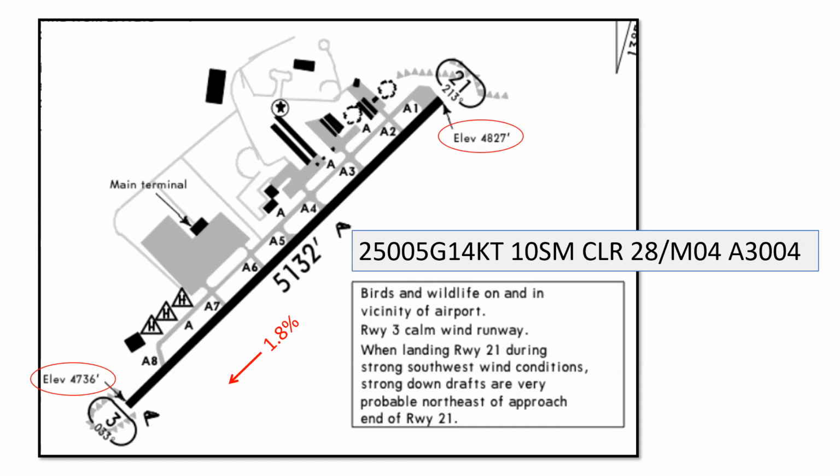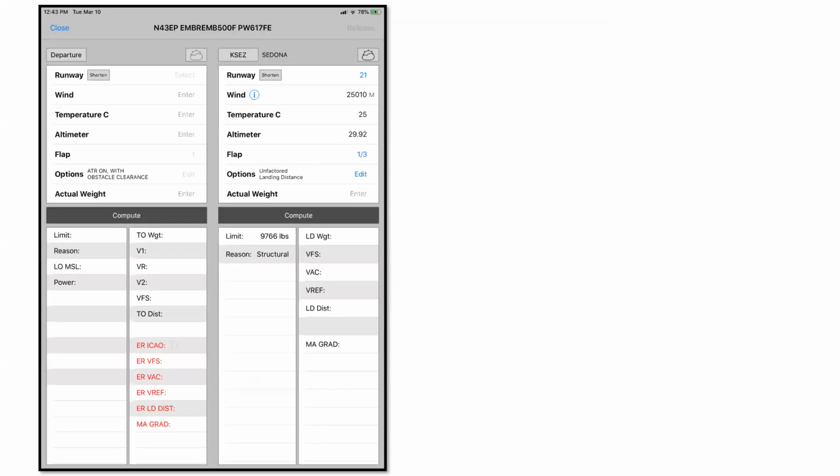We are allowed to land on slopes anywhere from 0 to 2% pitch. We could land with up to a 10-knot tailwind, and we don't really have any certified limit of how much headwind we could land into. We all have our SOPs that might limit what the absolute winds we'd be comfortable landing in are. But the point is, there's quite a range of slope and wind conditions that we might be facing. And to try to intuitively decide at which point the tailwind uphill is safer than the headwind downhill is just not likely. So using runway analysis, in this case the iPreflight app,